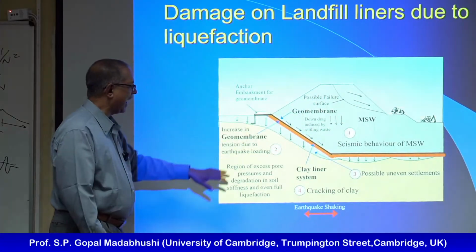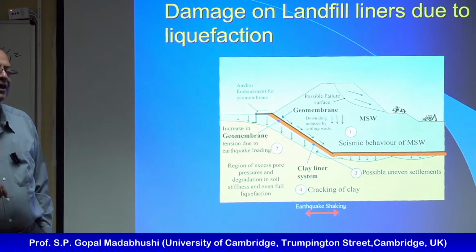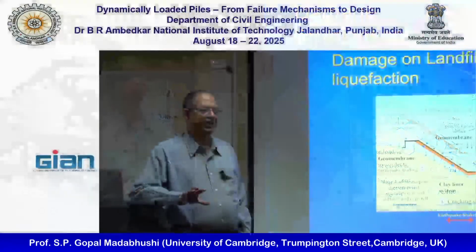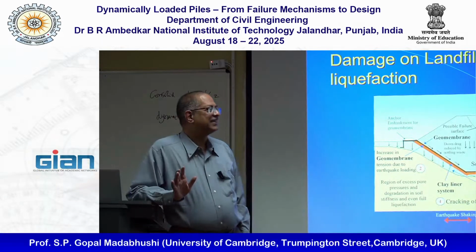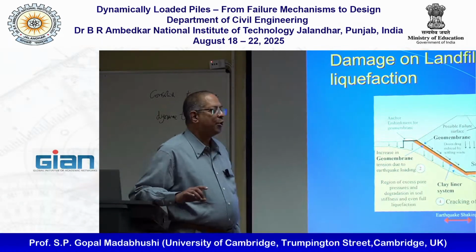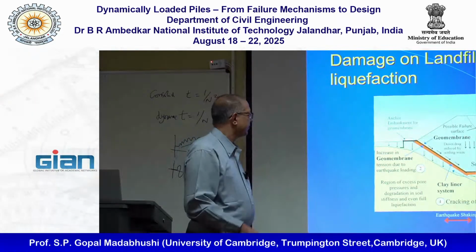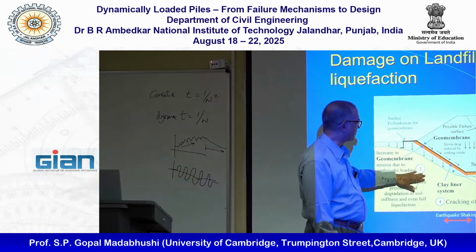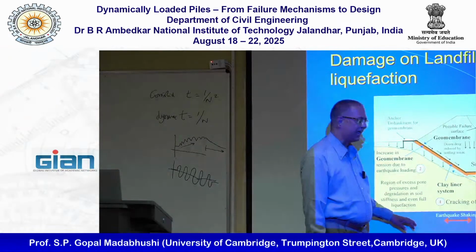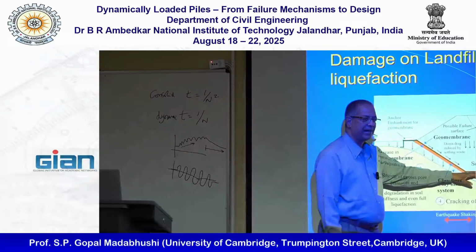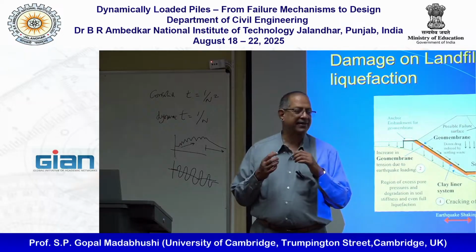Now these type of landfills have been built in California, Southern California, since about 1950s, okay? And nobody has worried about if I have sand below and if I get an earthquake, I could liquefy the soil and that can lead to uneven settlements. And these things are very sensitive to cracks.